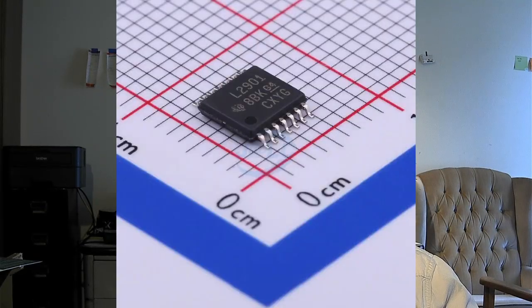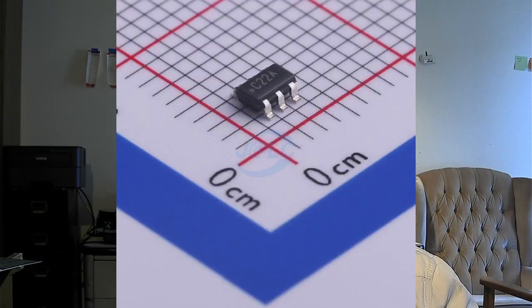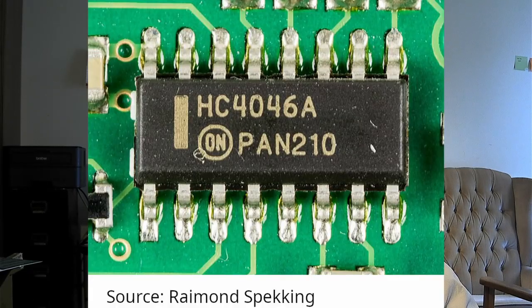There's also options like the MSOP, the TSSOP, the SO, and countless other packages. If you are picking a surface mount package, do pay attention to the pin spacing. The SOIC has a 50 mil pin spacing, which is still wide enough that you can solder it by hand if you have a good soldering iron. But if you get down to the MSOP, they start to get really close together, and soldering by hand takes a lot more skill. If you're getting your circuit prototyped into a PCBA, and you're just having someone else assemble your board for you, you don't have to worry so much about the pin spacing, but remember, if you rework it, you will have to solder it at some point.